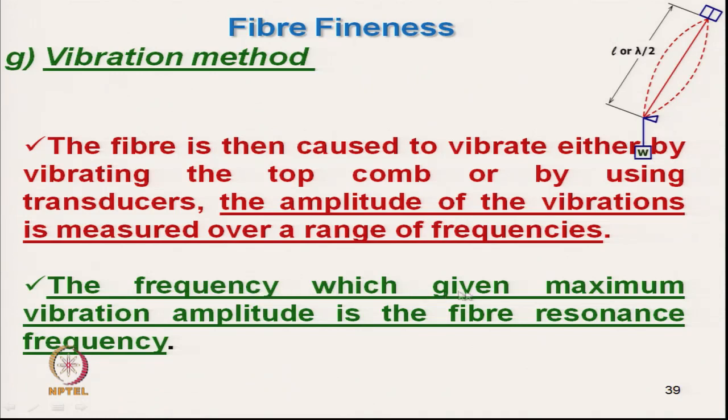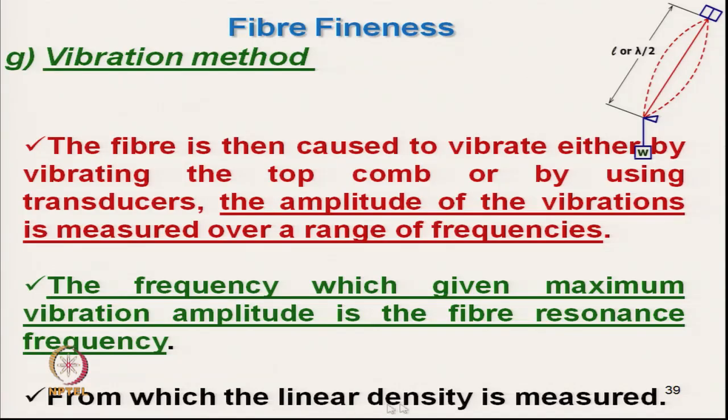The frequency which gives the maximum vibrational amplitude is the fiber resonance frequency. That frequency f is taken for calculation, from which linear density is measured.